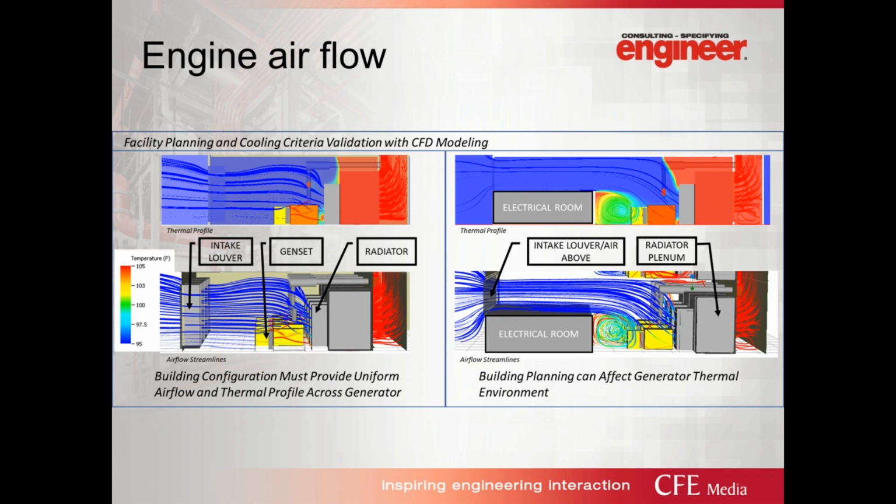So we recommend using CFD modeling, computational fluid dynamic modeling, to model the airflow that helps dictate and inform the form factor of your room and how the air is going to be going across those engines from the inlet through the radiator discharge as well. Many a time have we modeled something and found that it was inappropriate and you were going to have a problem with engines overheating. So CFD modeling traditionally was used only for white space cooling, computer floor cooling. We are using it now for generator cooling as well, and we recommend doing that as early as you possibly can in the project because that's going to dictate your architecture.